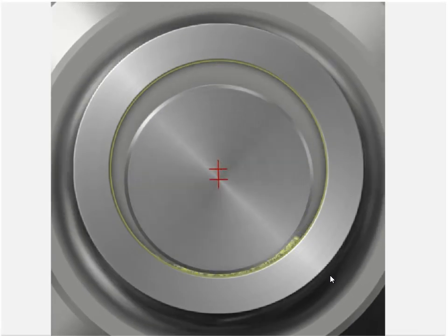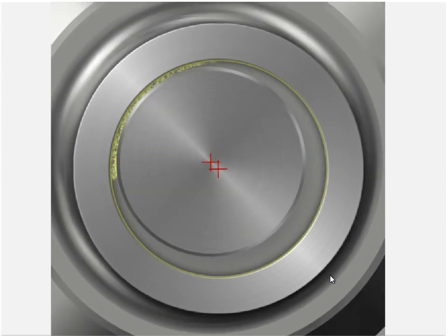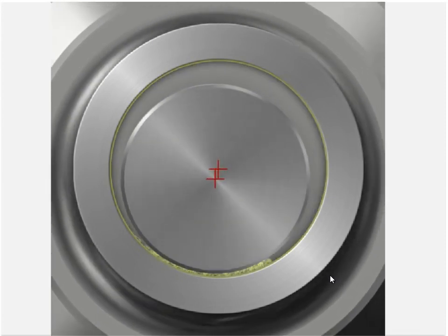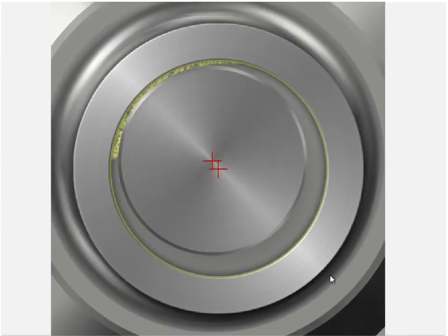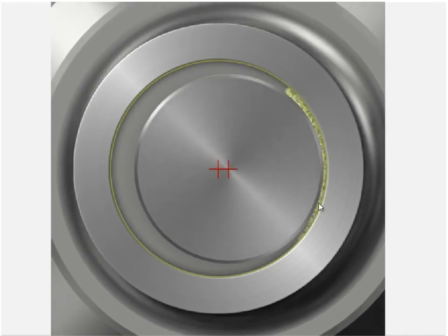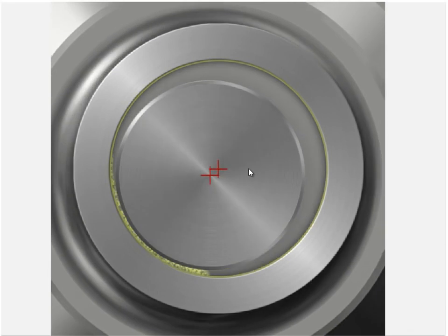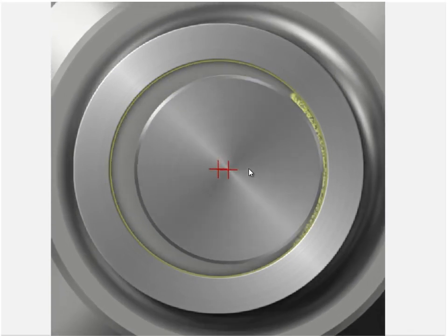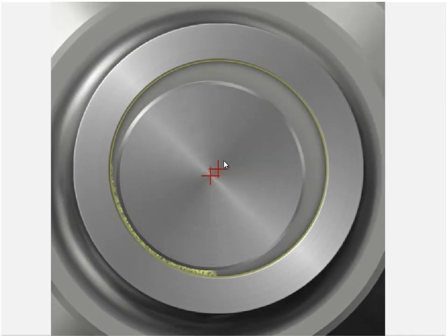And one of the ways we would, what we'd like to be able to tell is just what is the rotor doing, what is the journal doing within that bearing. In this instance, we have oil whirl. This wedge of oil is actually following the shaft around as it moves in this big wide motion. It's using up all of the clearance that's available, hopefully still keeping that wedge there, but this is quite high vibration.